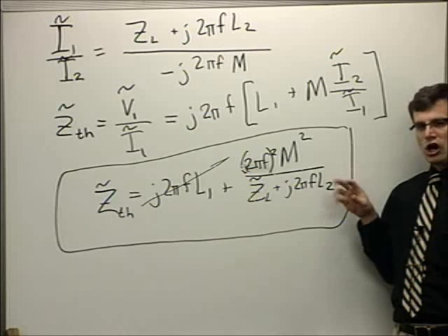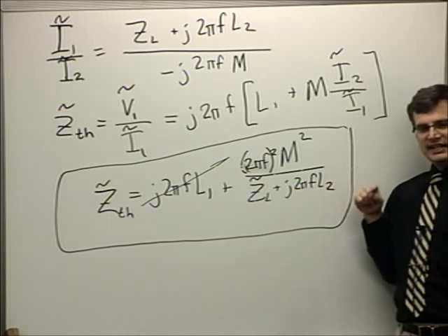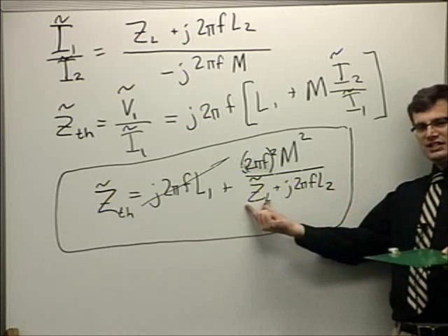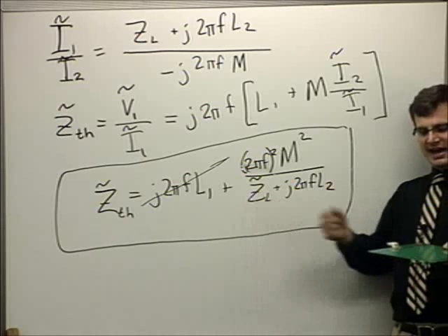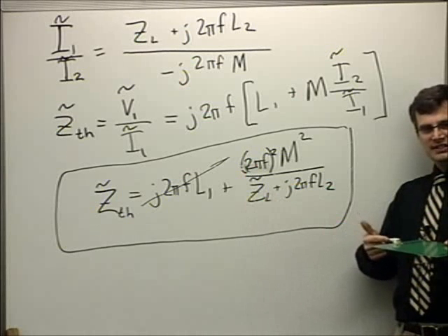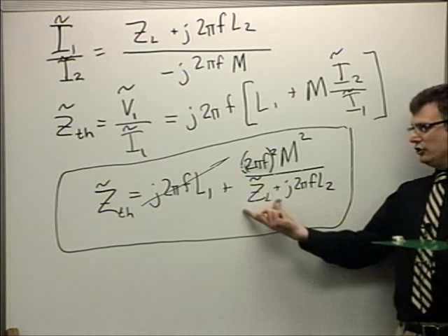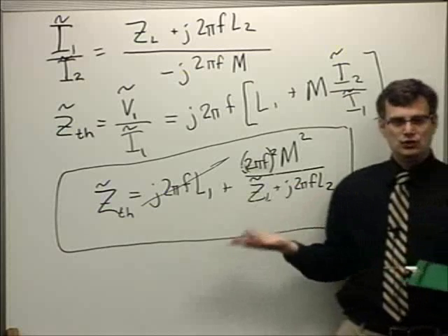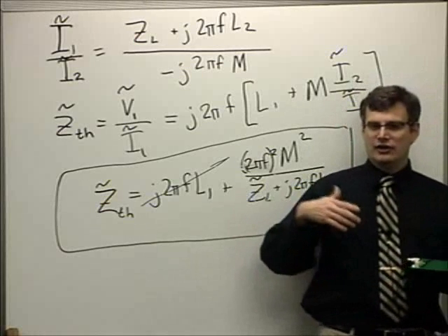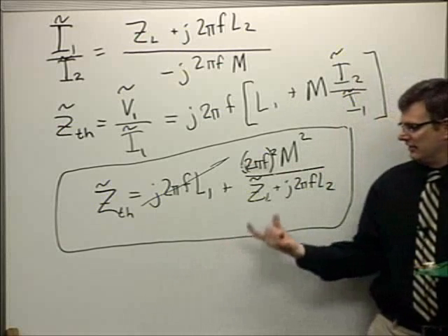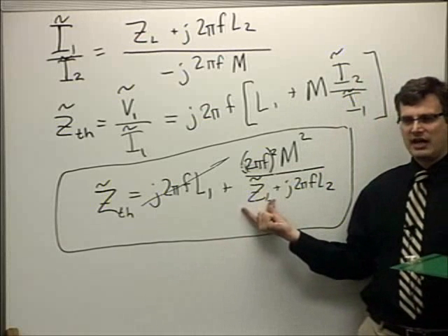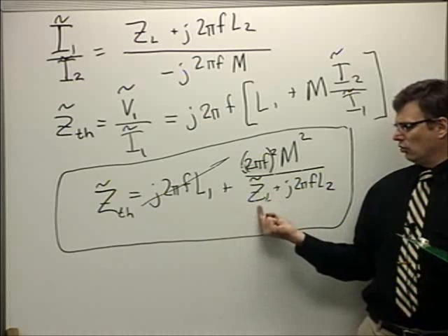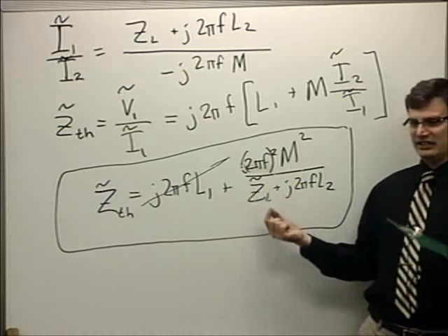So your card wakes up. How does it get the information back to this port? Well, it switches in different loads. And if you just monitor the equivalent impedance here, you will see the chip as it changes this term. And it usually alternates between two states: an ohmic matched type of state that makes this purely resistive, and a short circuit, which makes this 0, or an open circuit, which makes this infinity.